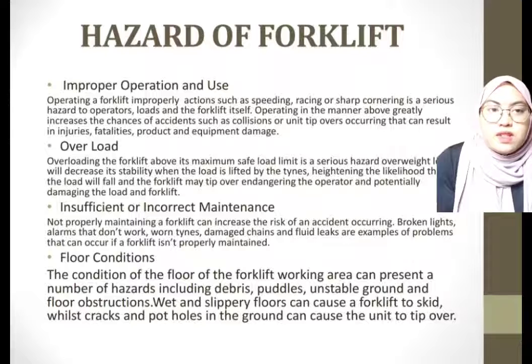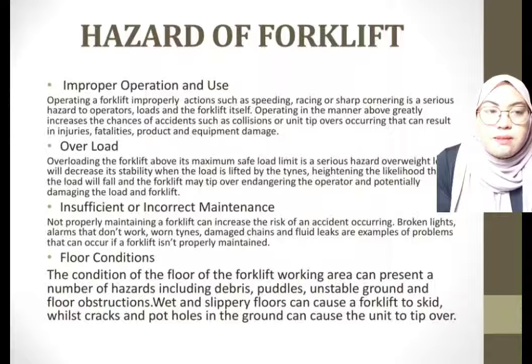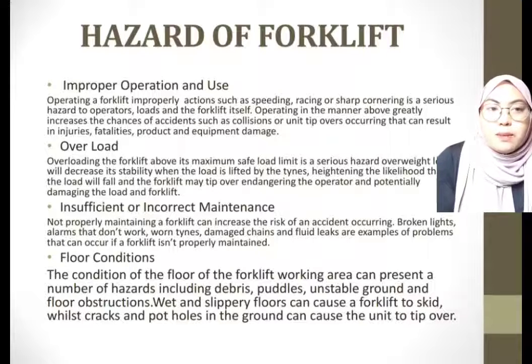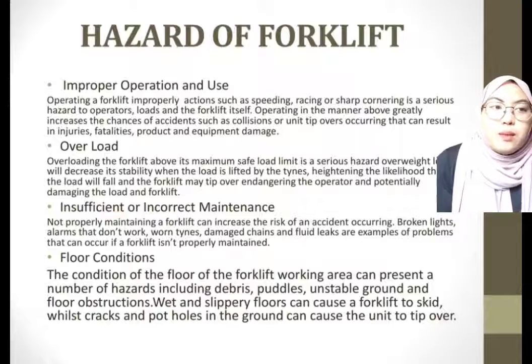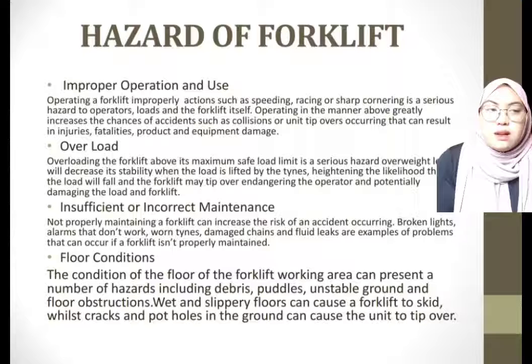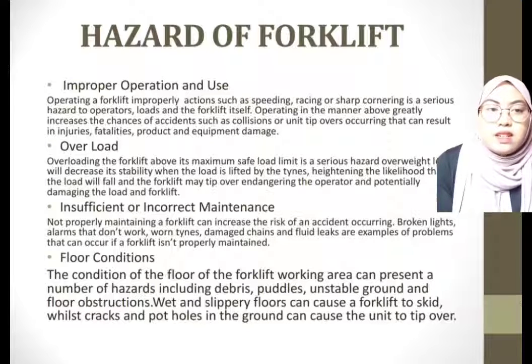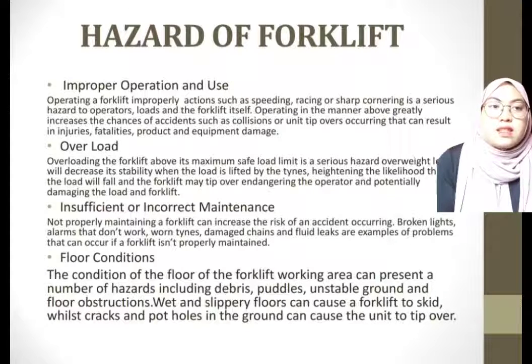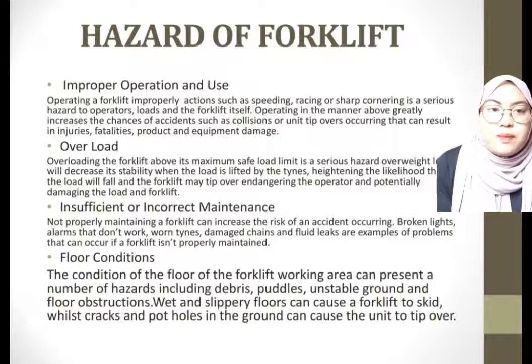Thirdly is insufficient or incorrect maintenance. Not properly maintaining a forklift can increase the risk of an accident occurring. Broken lights, alarms that don't work, worn tines, damaged chains, and fluid leaks are examples of problems that can occur if a forklift is not properly maintained.